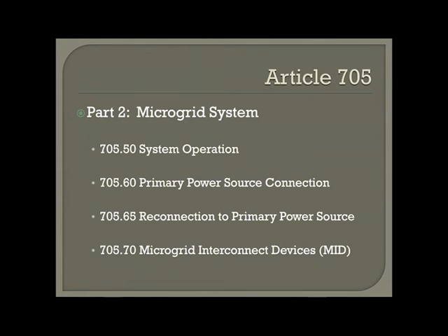Don't put any current transformers in there. Don't run through that with some wires just because it's easy to get into the panel in the basement. Do it the correct way. Stay out of that meter. Go to your disconnect, mark your disconnect, mark your meter. So what if you're not even going inside to the electrical panel? Go down there and put a sticker on there telling me that.